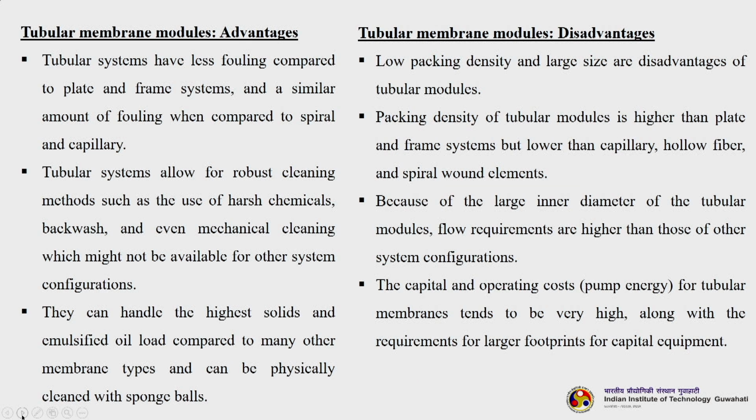So, let us go ahead and understand their advantages and disadvantages. Tubular systems have less fouling compared to plate and frame systems. They allow robust cleaning methods such as use of harsh chemicals, backwash, and even mechanical cleaning is possible. They can handle the highest solids, as we have already discussed, the highest TSS, TDS and emulsified oil load also. The disadvantage is low packing density and large size, so carrying and transportation also is a problem. Because of the large inner diameter of the tubular modules, flow requirements are higher than those of the other system configurations.